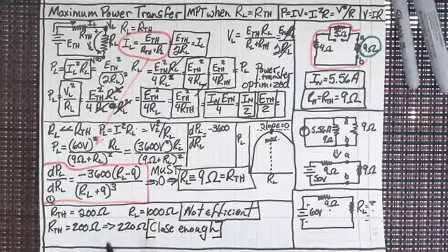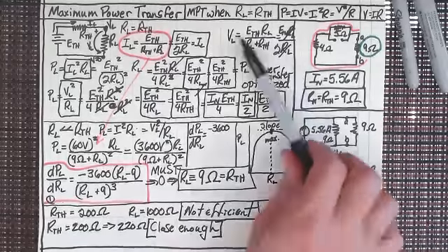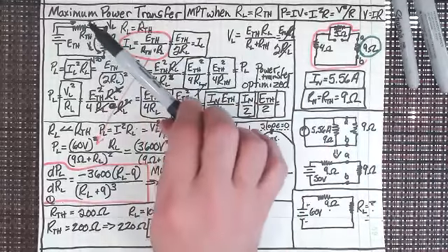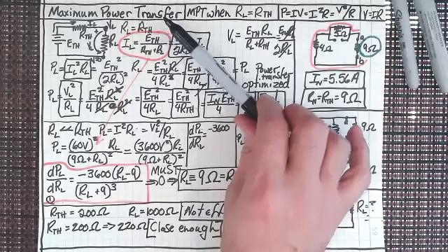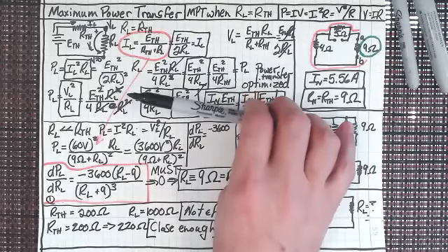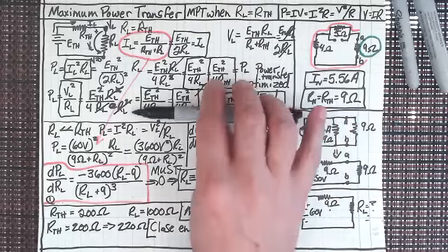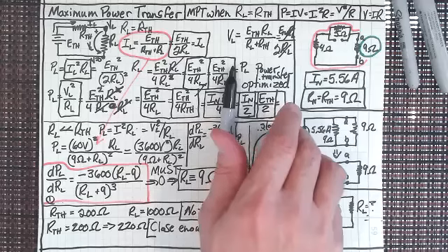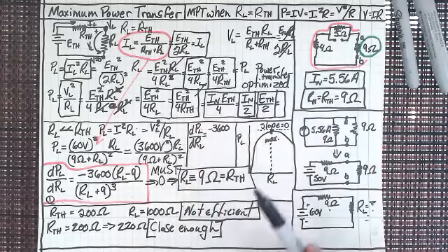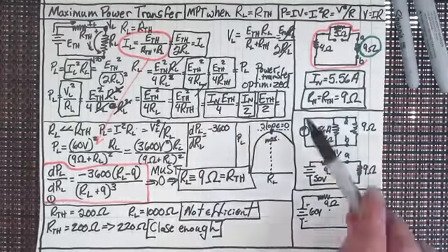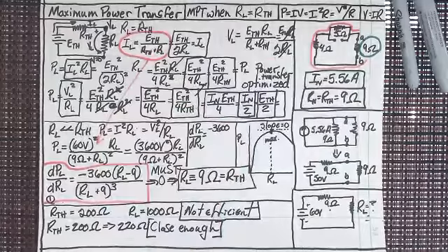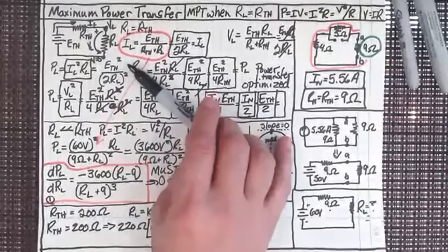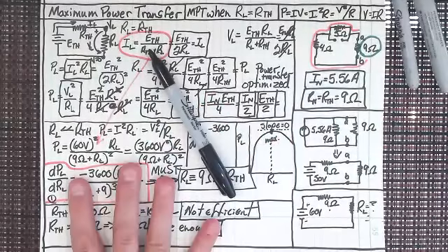That's the thing I want you to take away from this lecture: with maximum power transfer, when you're trying to transfer something through there, you want to make sure that whatever the resistance is in the circuit, or whatever type of voltage source you have, and the internal resistance of that, is going to mate up with the type of load that you're going to put on that circuit. Does everyone understand that? Why we use this maximum power transfer, and that's why I derived all this.